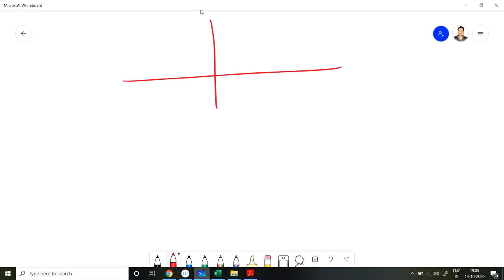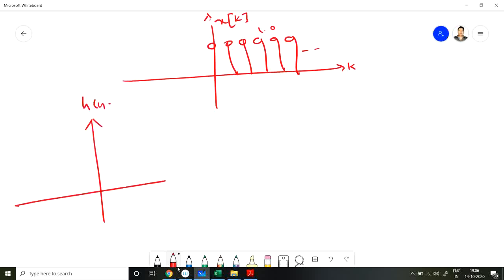So this is our x[n]. Let us write this x[k] because we have to find out that convolution. So x[k] is basically equal to u[k]. Then we have h[n minus k] for n less than 0.